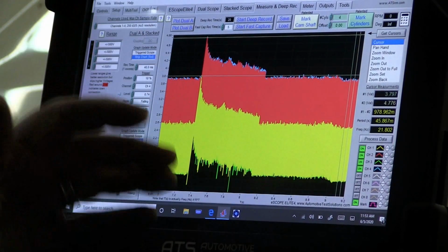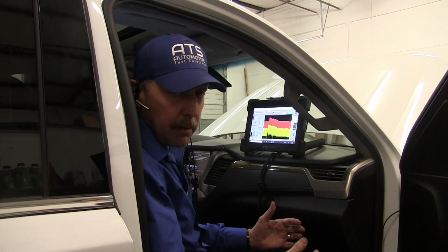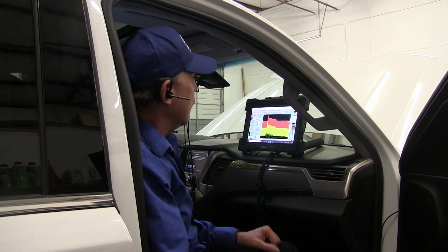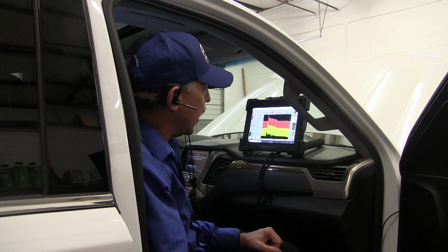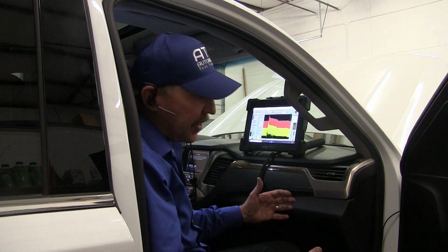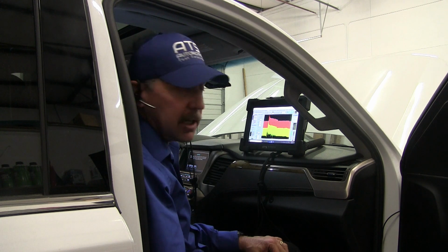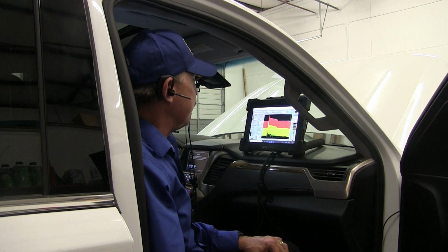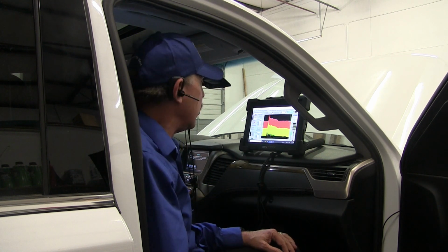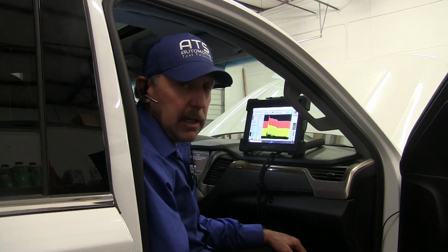So that's a volt drop that it's moving the bus up with. Now that could be a problem, but I'm not going to look at that right now because I don't think that's my issue. But that's some kind of a voltage drop off of the starter. When we have 1,500 amps or so, 1,000 amps rushing into the starter, we have this drop that's being seen in the bus structure. But I don't believe that that's my problem, but I definitely wanted to show you guys that so you can see it.